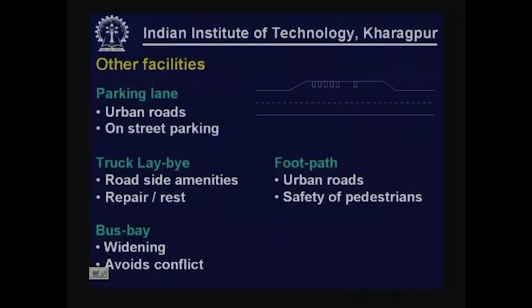Often parallel parking is done under parking lane. Of course, other types of parking like angular or perpendicular parking are also possible. The purpose is generally the same, providing extra width, but if it is provided for trucks so that drivers can access roadside amenities and also stop the vehicle for repair or maintenance purpose, the extra width is known as truck lay-by.